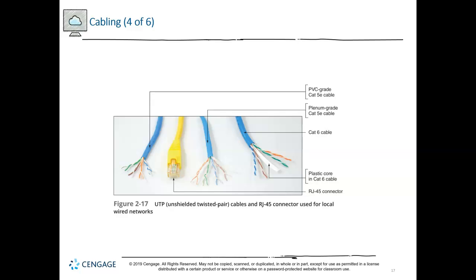Your signal can cross from one wire to the other. The way we avoid that is we want to cross at 90 degrees. So if I now take my arms and I twist them around each other like this, that's the same thing I'm doing with the wire. And the tighter my twist, the closer to that 90 degrees, and the better I can reject foreign signals coming in on that line.